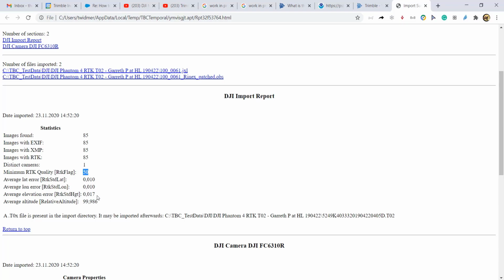In the future, this would definitely be something interesting to discuss, whether we could already go with this data into relative adjustment and absolute adjustment without measuring a single ground control point. But as we are not sure about the real quality of this and also no protocoling is available, we recommend to first run the baseline processing in TBC with the data.